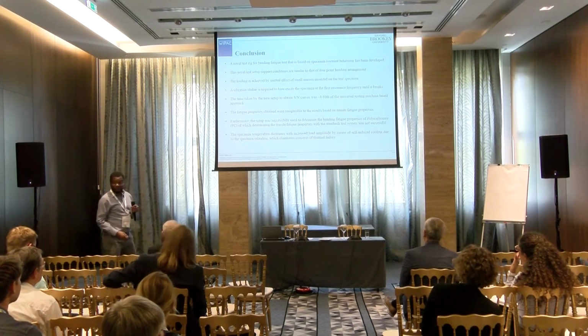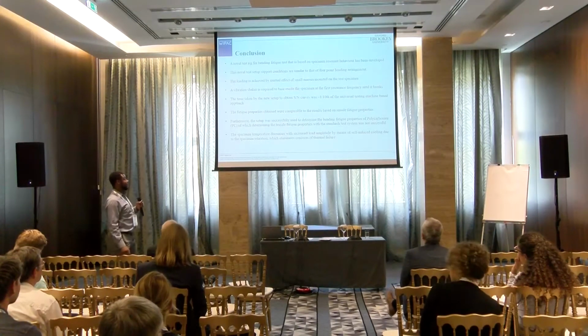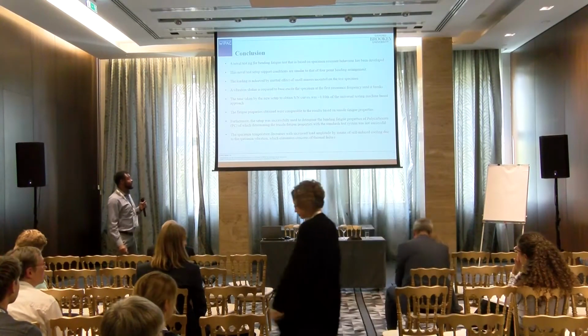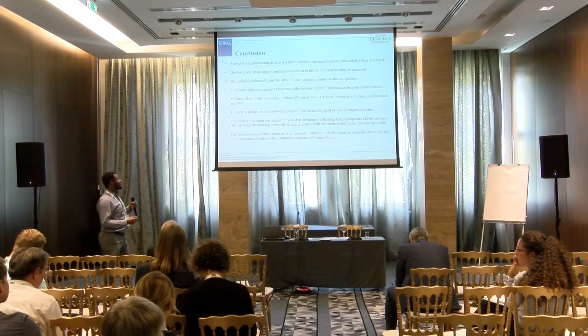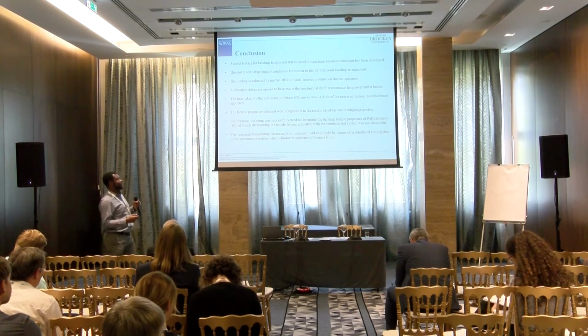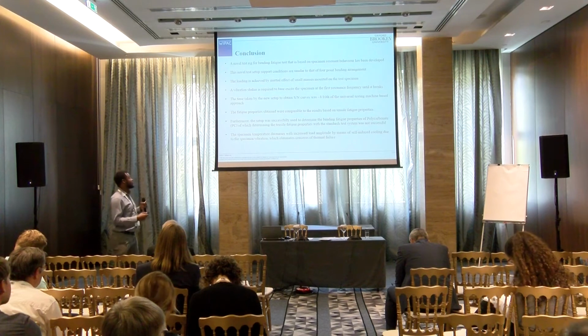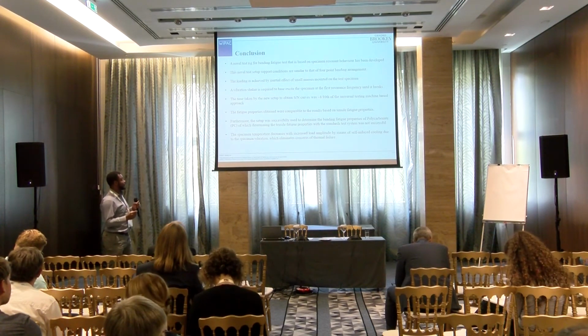So, in conclusion, a novel test rig for bending fatigue tests that is based on specimen resonant behavior has been developed. This novel test system's setup support conditions are similar to those of a 4-point bending arrangement. The loading is achieved by the natural effect of small masses mounted on the test specimen.